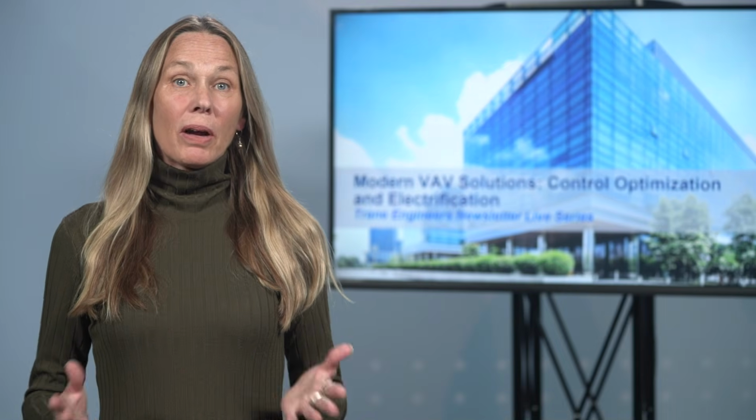We have talked about all these optimization strategies for VAV systems, but do we know how much better they make our buildings? Next, Mayra will show us a case study. Let's look at this 30,000 square feet office building in Kansas City with 2 VAV rooftop units, each with a dozen VAV boxes. In 2019, the occupant reported high demand peaks during winter mornings. Reducing demand was the customer's priority since they had demand and ratchet demand charges.